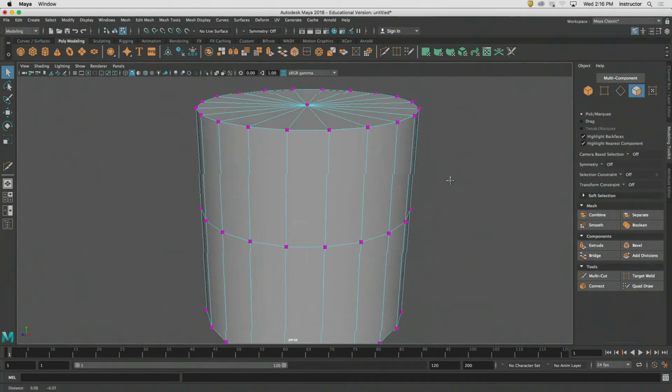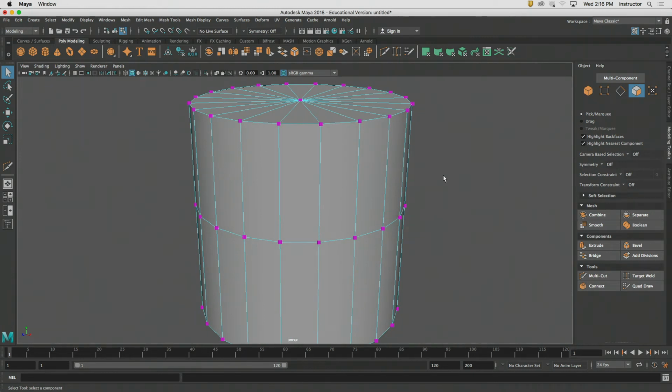Now that we can see our verts, we can see exactly what the backspace key is going to do. I'm going to flip over into my edge selection state and simply double-click on an edge loop to select all of it. Now, if I was just to hit the backspace key, look what happens. All the verts that were on that surface and that created that edge loop remain in the surface itself. Thumbs down, massive thumbs down. This is going to cause huge problems inside of our modeling sequence if we're unaware of it. This is an often stumbling spot for people.